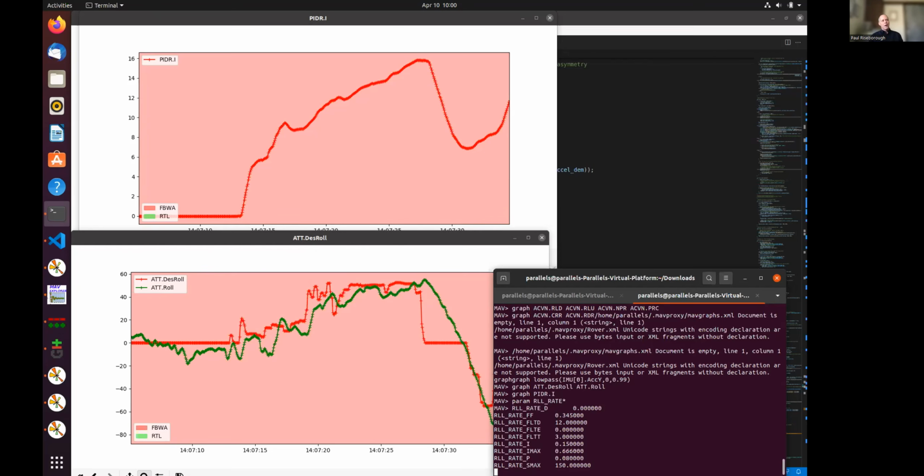So I raise this because something to watch out for is the build up of side slip with a twin engine aircraft, because there's an assumption that I've got two identical electric motors, I've got two propellers of the same manufacturer, same model, same diameter and pitch, everything's the same. I should have an aircraft that's not side slipping, and that's not necessarily the case.